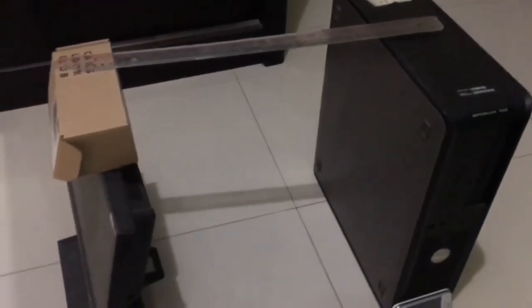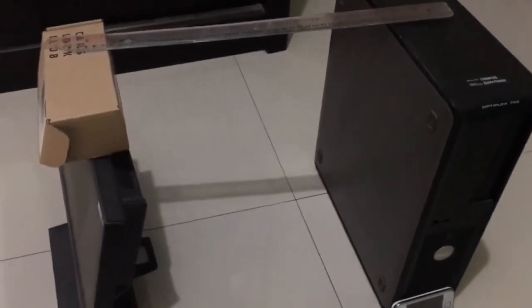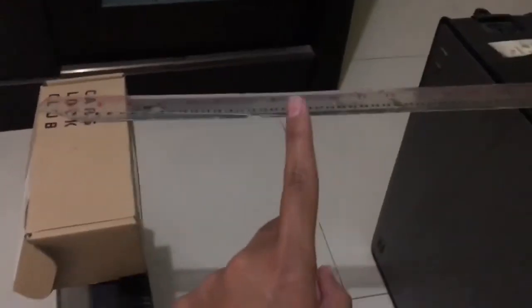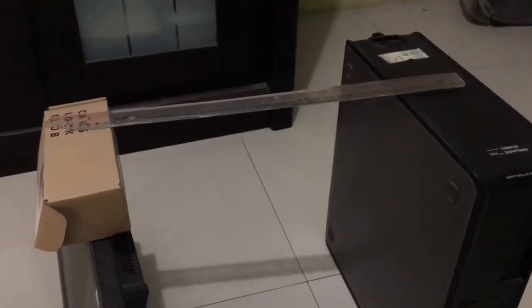And one other thing, before we put the mass, we need to measure the length between this point and this point, and from this point to this point. After we measure the length, we see the digital force reading, and then we can multiply the result and find the bending moment. That's all for the bending moment experiment.